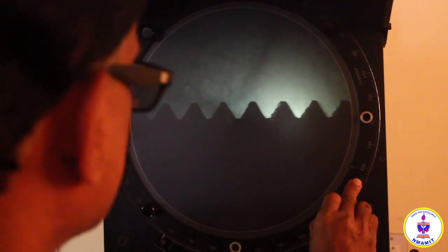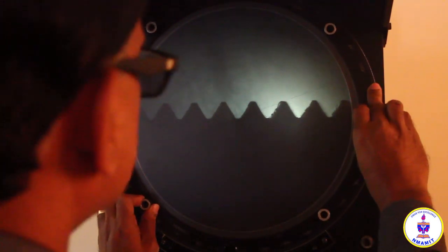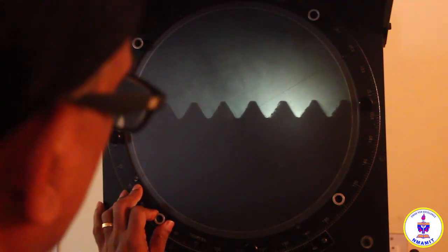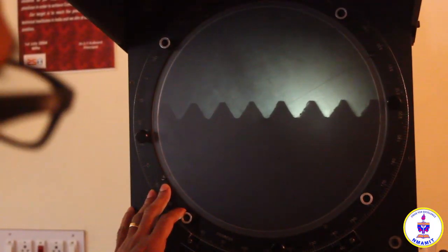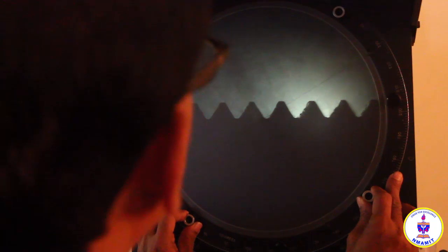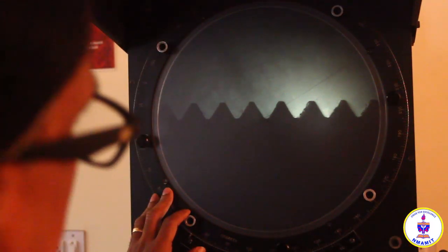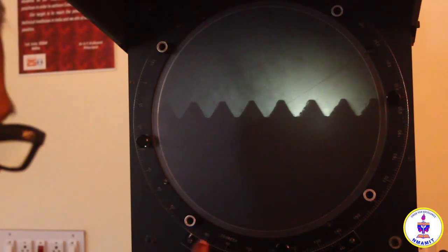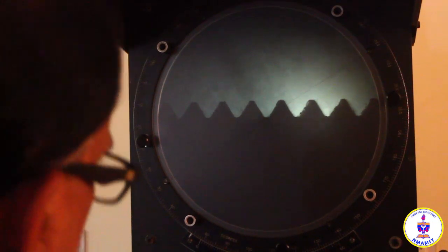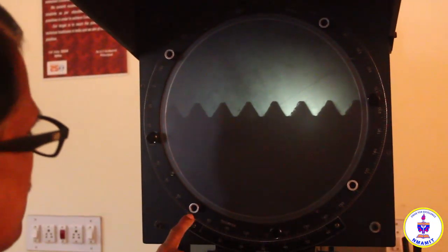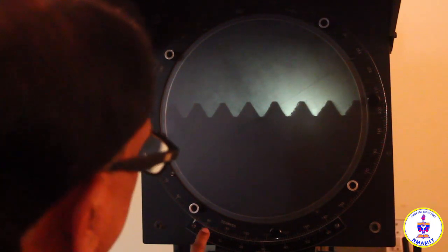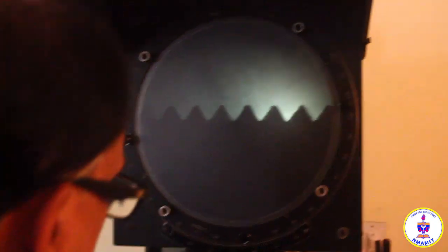So rotate these screens such that one of the cross lines is brought tangential to or parallel to the flank on one side. So it is adjusted and brought parallel to the flank on the left side. Right. Now on the protractor here you can read the angle. We have this 60, 70, 75, 78. It is 78, and here the vernier is there, which is one division is 1 degree.